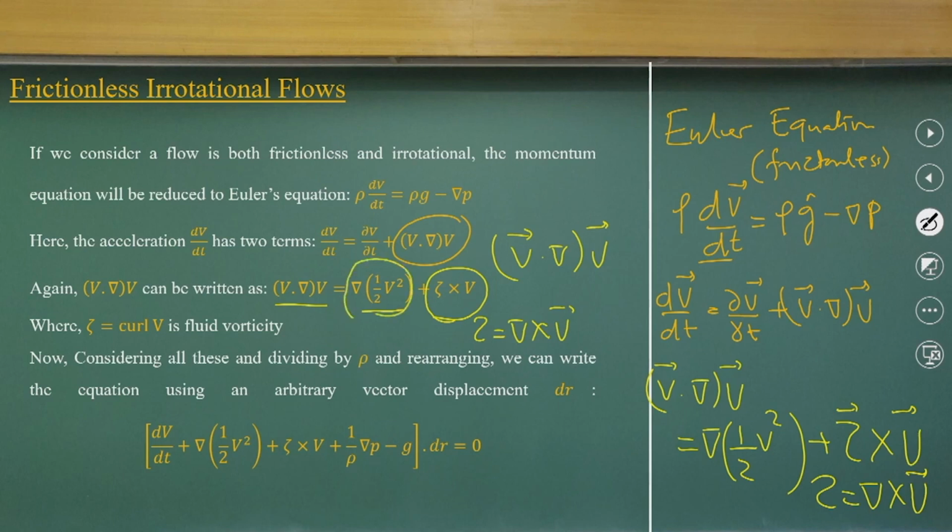Try to remember that this component is there in the Bernoulli equation. The idea is to take this form so that we come close to the terminology of the Bernoulli equation. We know there is a pressure component in the Bernoulli equation, a V square component, and the rho g term, so we get the three heads. But there is a new component we get by deriving these equations, the cross product between the velocity curl and the V vector.